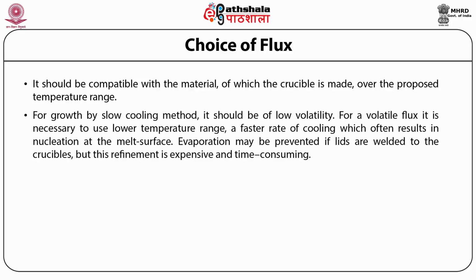For a volatile flux, it is necessary to use a lower temperature range and a faster rate of cooling, which often results in nucleation at the melt surface. Evaporation may be prevented if lids are welded to the crucibles, but this refinement is expensive and time consuming.